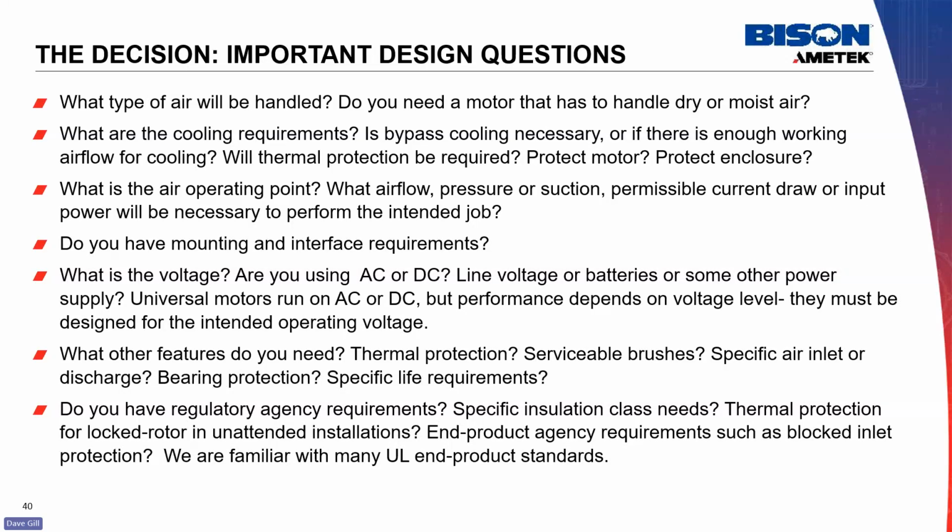What other features do you need? Thermal protection, serviceable brushes, specific air inlet or discharge, bearing protection, specific life requirements? Do you have regulatory agency requirements, specific insulation class needs, thermal protection for locked rotor in unattended installations, end product agency requirements such as blocked inlet protection? We are familiar with many UL end product standards, and a number of these tests we can do internally to help you in your development.